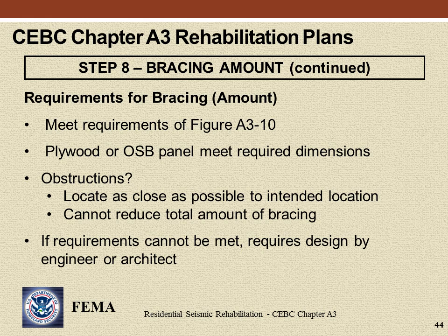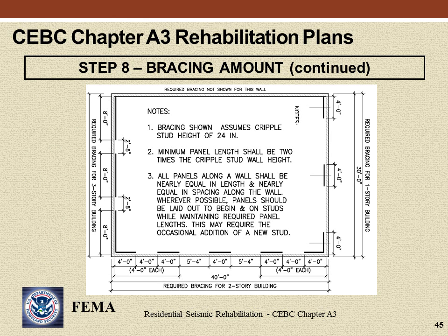Step 8. In addition to meeting the required percent of wall length per Table A3-A, the requirements of Table A3-10 for distribution and amount of bracing must be met. Where these requirements cannot be met, design by an engineer or architect is required. In addition, the following are required for bracing.